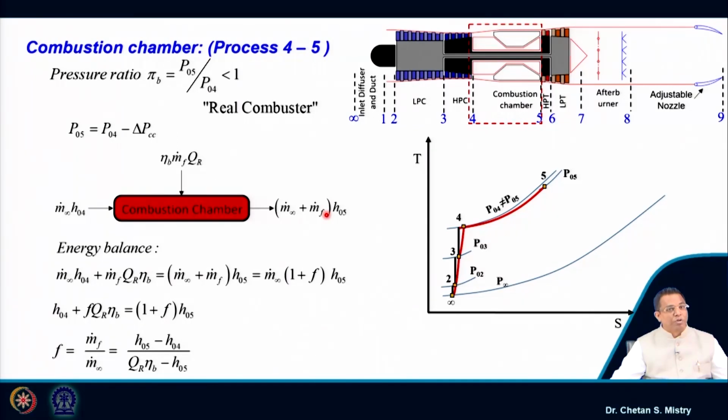Again, let me put the point here, many times this fuel air ratio is known to us from the required specific fuel consumption. Under that condition, we are interested in calculating our turbine entry temperature. So, you can do this calculation both ways. So, be careful about this part.